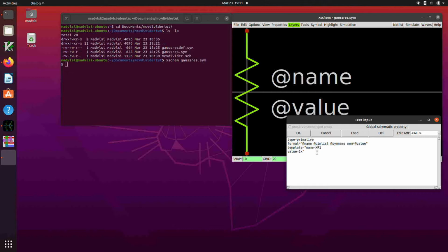We're going to get a subcircuit reference, and then we'll have another symbol which contains the subcircuit definition, which has a resistor in it with the Gaussian variation. And we're going to have the ability to turn that on and off with a parameter called MC switch, just like we have set up for the Skywater 130 technology with the FETs.